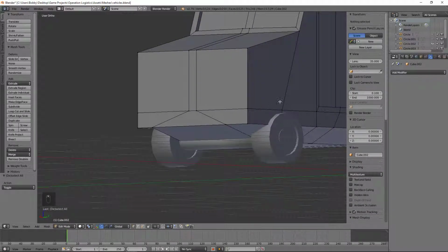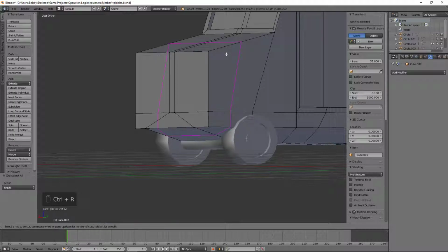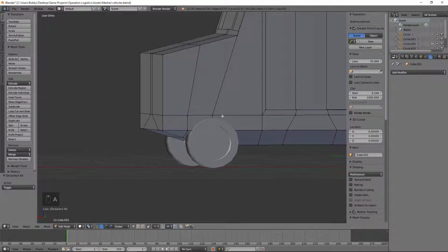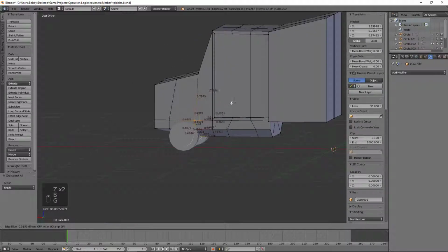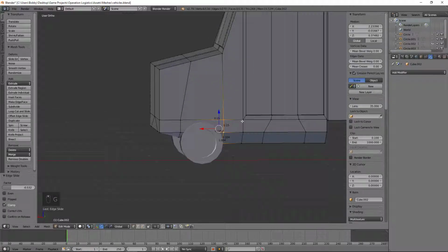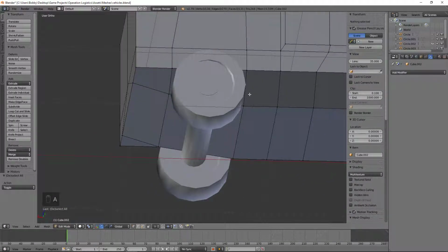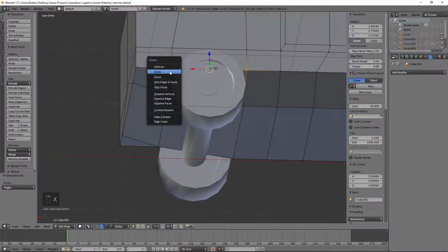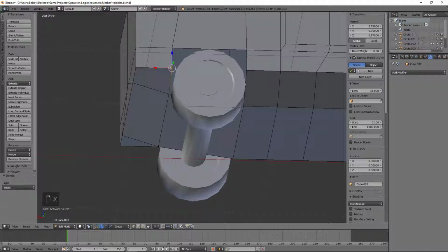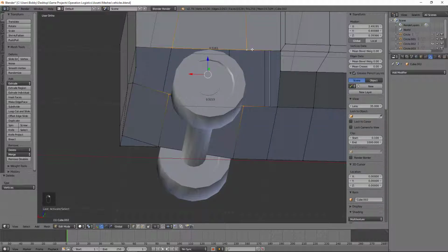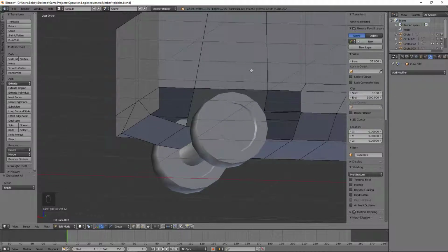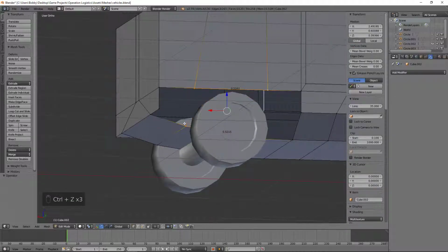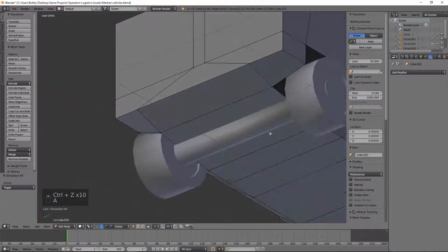And then the question is, how are we going to go about creating a wheel well here? Well, we'll need an edge loop there for sure. And then we can go ahead and grab this edge loop and just slide it back over here. About like that. And then we can make this into a wheel well by deleting this edge. And perhaps even deleting these vertices full on. And doing something kind of like that. No, I don't like that. Let's bring those vertices back.